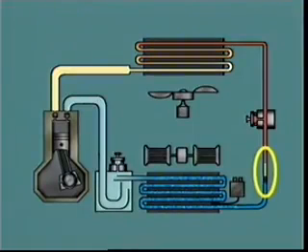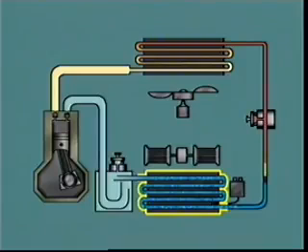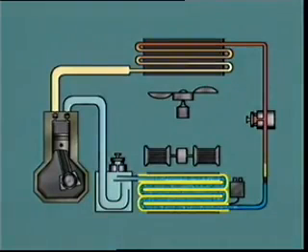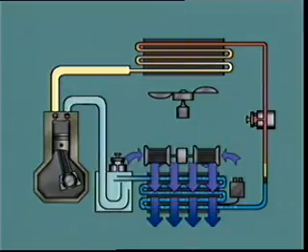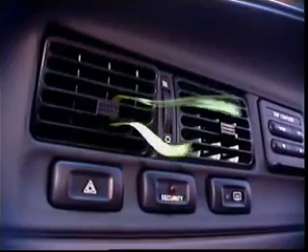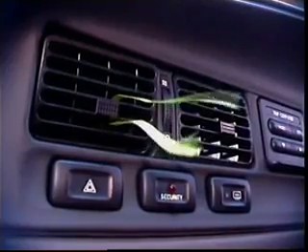The liquid refrigerant loses pressure by flowing through the fine tube and is then forced to expand suddenly by passing through the nozzle and entering the larger volume of the evaporator. The drop in pressure causes the low pressure, low temperature liquid to boil, and this liquid mist evaporates rapidly in the evaporator coils, absorbing heat from the air passing across the external fins. The cooled air is directed to the interior of the vehicle by blower fans.